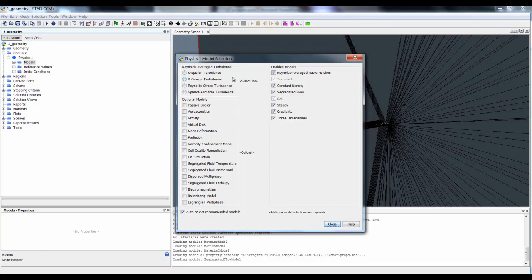It is robust, behaves well near walls, and does well in recirculation regions, such as bluff body protrusions, base drag, and so on. Either low Y plus or all Y plus, and I'll cover what this means in a moment. Boundary treatments can be used with this model. This model works best when complex geometric protrusions exist, bluff body separation occurs, and at supersonic speeds.